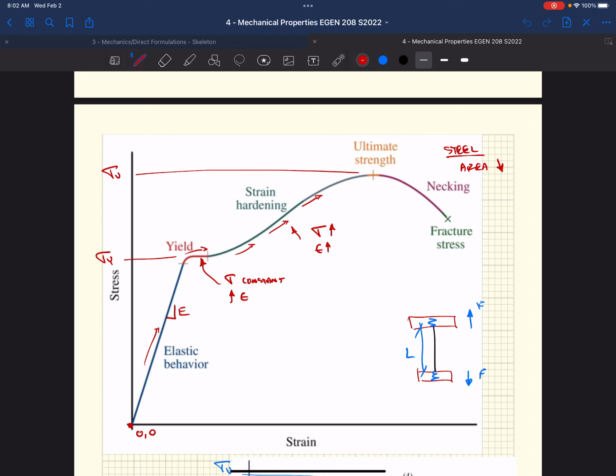And we plot that behavior, the stress-strain response, and we get a curve, something like this, for something like steel or a very ductile material. Something that undergoes a lot of permanent deformation. Anything beyond this yield point on the strain is permanent deformation. We're not going to get it all back. All we're going to get back is coming back down the elastic curve.